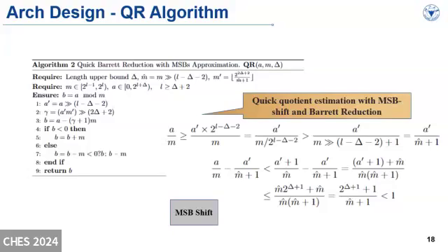Specifically, using only delta plus 2 bits of the divisor can constrain the final error of the quotient within 1. And with the help of MSB shift, we can quickly compute the quotient of the 3000-bit division with a quite small one. The small one only needs 160 bits.